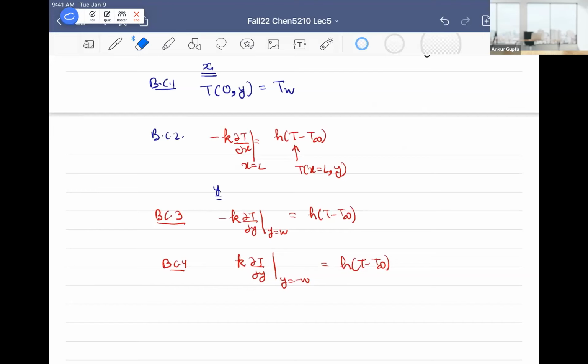The y direction, because I am taking a derivative in the y direction, and my y direction is of the length w. The formula is hw by k. I see h here, I see k here, and the delta y is basically roughly on the scale of w. So this is something we'll do again and again in the class: order of magnitude analysis. Order of magnitude analysis is not trying to solve this boundary condition, but trying to estimate what it tells us.